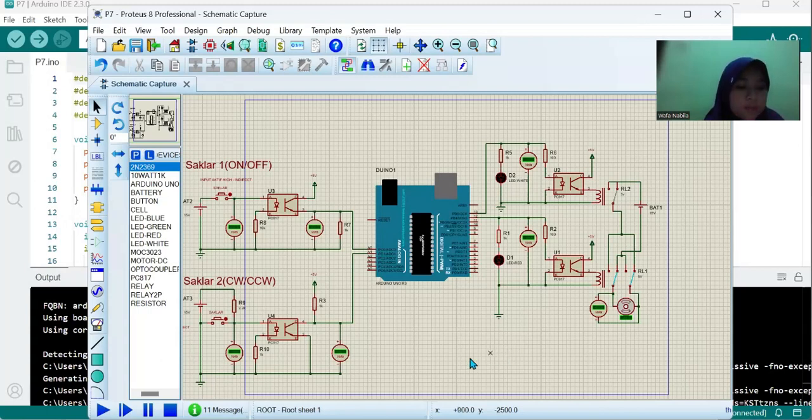The circuit starts from the pin input, which contains a button to turn the voltage on or off. The upper output determines whether to turn on the circuit, and the bottom one determines the motor direction, with the relay setting it to right or left, clockwise or counterclockwise.